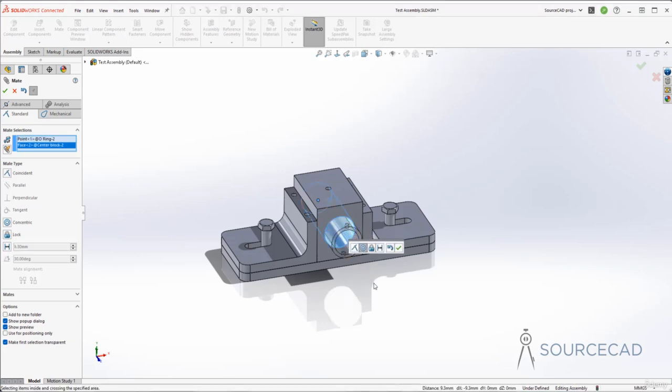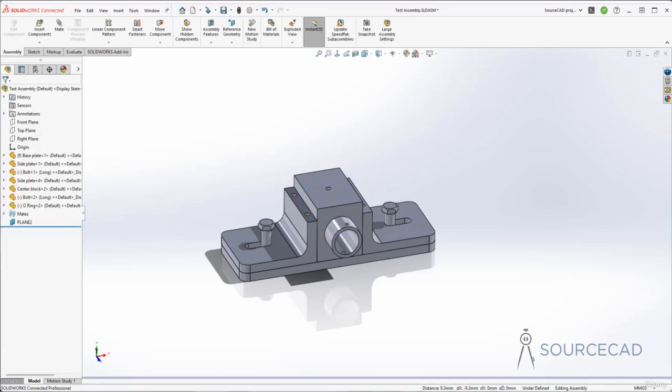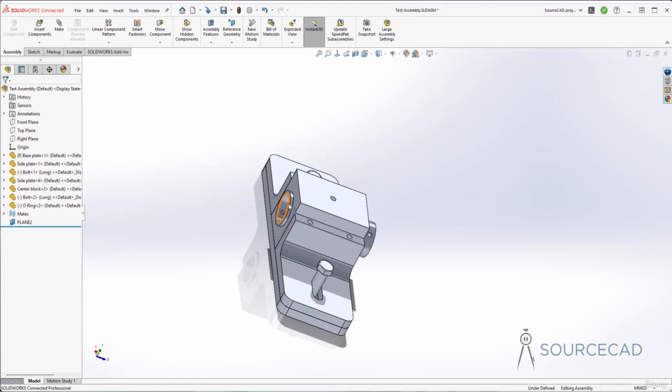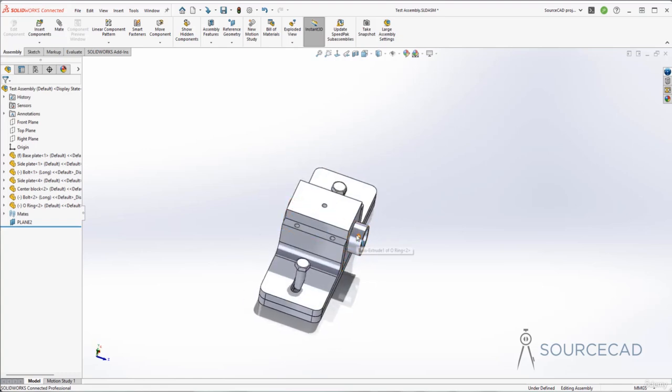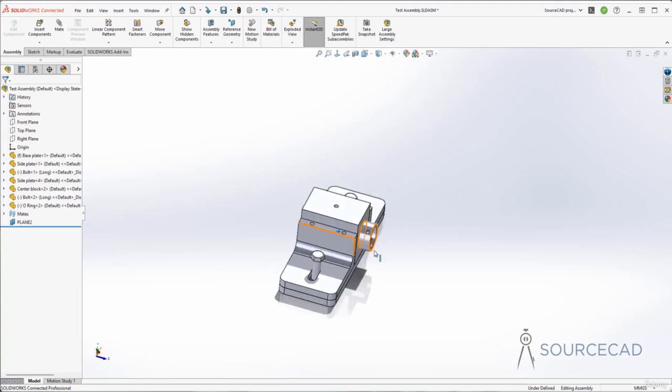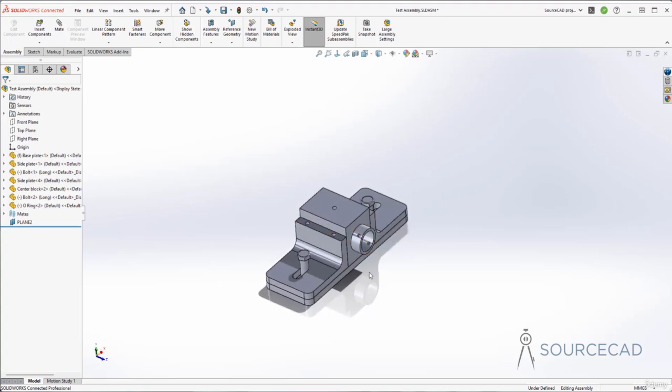As we have really good amount of freedom here, it is not rotating very significantly, but as you can see, there is a slight rotation here, and here it is. It is just rotating, but let's just lock its to and fro motion, and then we'll be able to freely rotate it. Now to lock this to and fro motion, we can apply a distance mate. Now in this case, as you can see, it is moving out from both the sides, and we want it to move out equally. Actually, the distance is 5 units from this plane to this plane. So that's how much we want it to extrude outside from both the sides. So we can use distance mate for this.